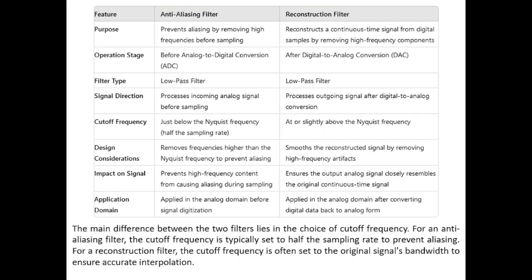Say for example, you are processing the ECG signal and you amplify the signal through the anti-aliasing filter. If you are applying a pre-processing amplifier and it is a part of your processing technique, it's okay. But technically your anti-aliasing filter will not have any gain.